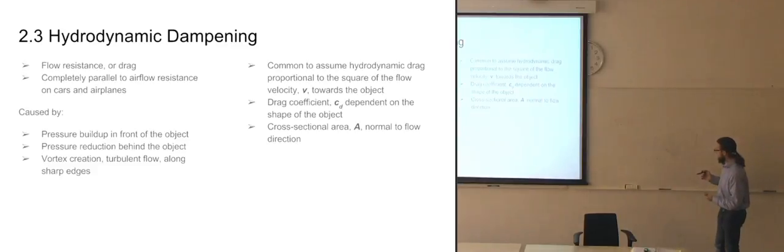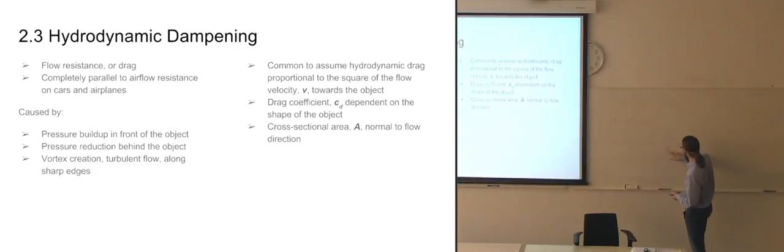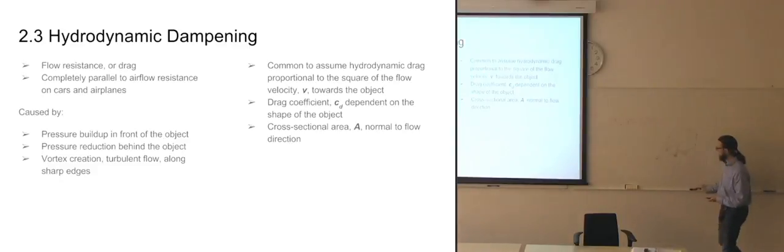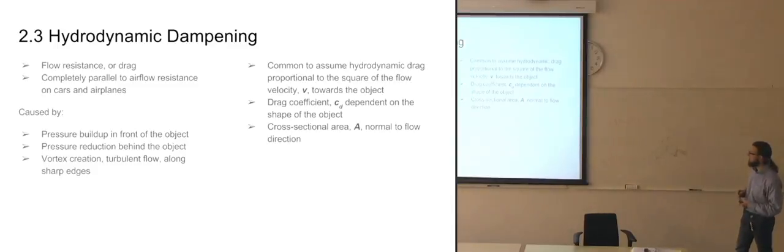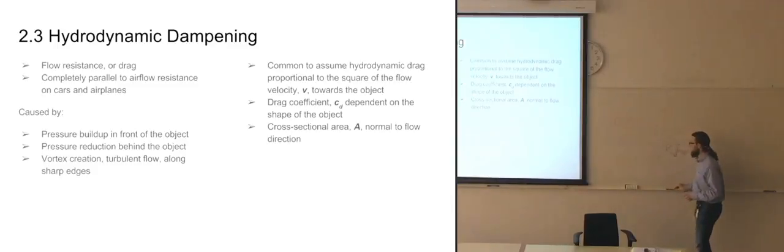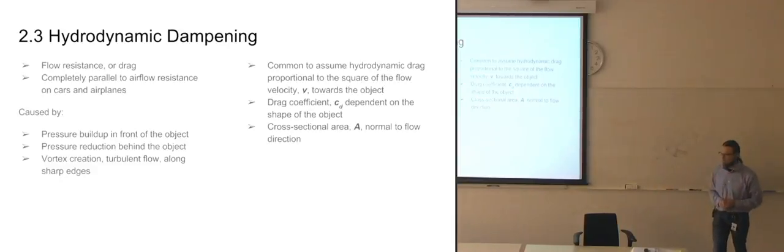But then, for an example, if this manipulator gets moved, they are often hinged fairly close to the edge here, and it's held off to the side at an angle, then you suddenly have to add the cross-sectional area that's sticking out of the main front of the ROV there. So that's going to be added to the rest of the cross-sectional area. So basically, it's whatever area that's hitting straight on the flow of the water.